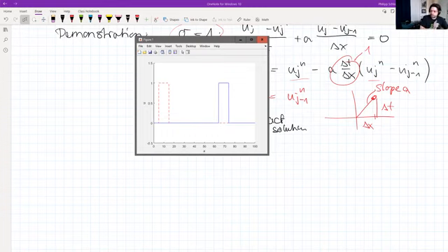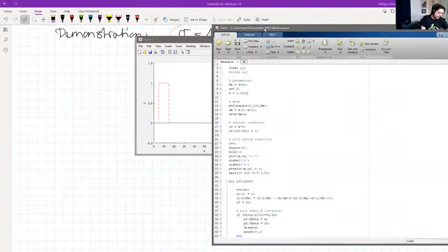Okay, now just before the break, I would also like to show you what happens if I start to modify my sigma. So if I go from 1.0 maybe to 0.5, so I have a CFL number of 0.5. I make essentially my time step half as large as it could be compared to the stability limit. So I'm not on the unit circle with my spectral amplification factor, but I'm having a circle with only 1/2 as the radius.